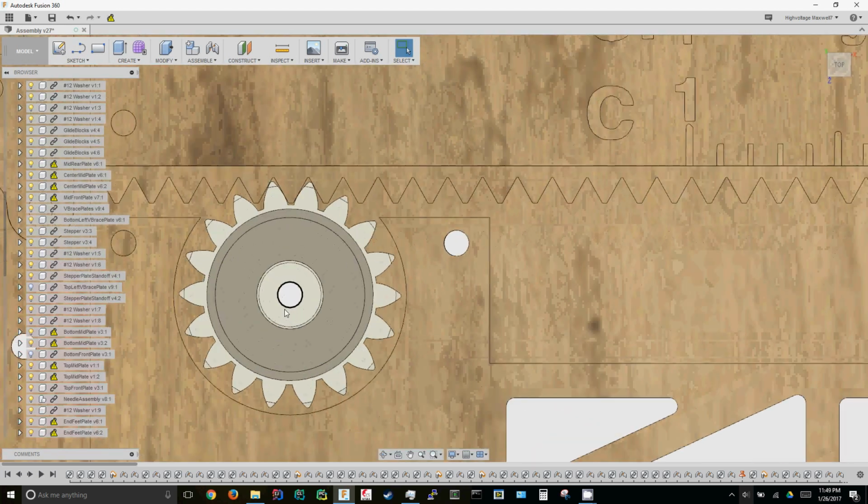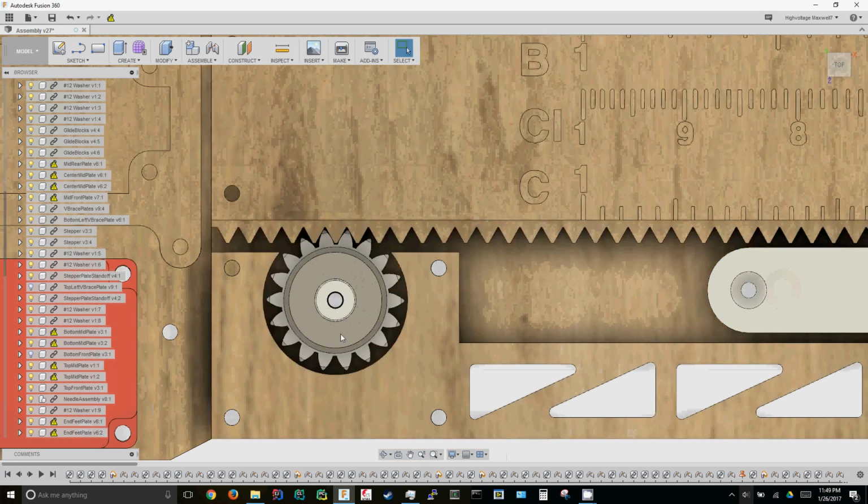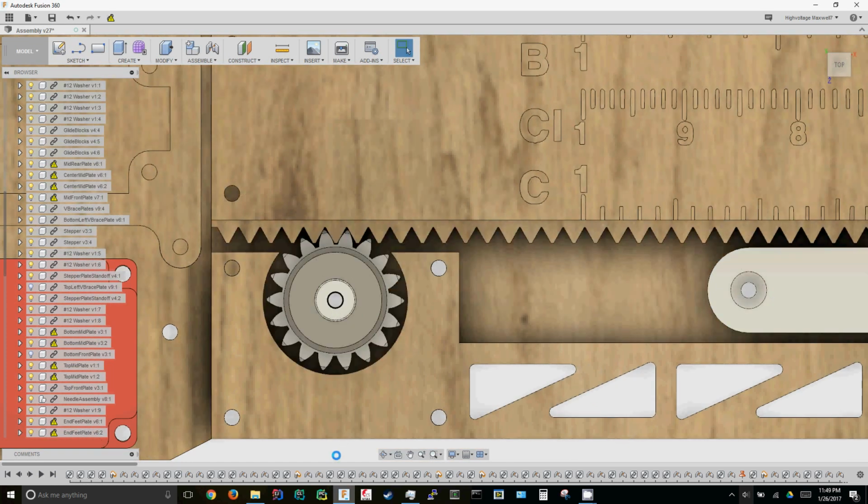Now I mentioned that this is going to be hard to make, mostly because I don't want to say a custom gear tooth pattern and size, but I don't want to say common, but it's one of the known indexes that people use occasionally. However, finding a cutter for it is going to be expensive. I'm considering using a high-speed steel blank and grinding it into shape so I can use it as a single tooth cutter, and just use an indexing head to rotate the UHMW block and cut the teeth into it as I go.